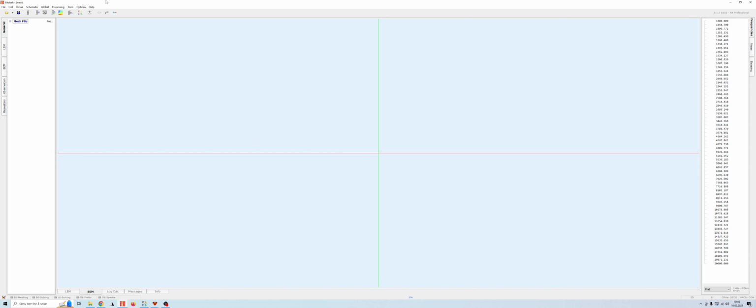Now that we've done this, we can go back to global and BEM parameters, and we can change to circular symmetric mode. And important, you cannot choose actual symmetry. I do not know why, but it gives you an error if you choose actual symmetry, so just say no symmetry and click OK. Now the view has changed a little bit because we cannot see the negative y-axis anymore. We only see negative, positive x, and then the y-axis.